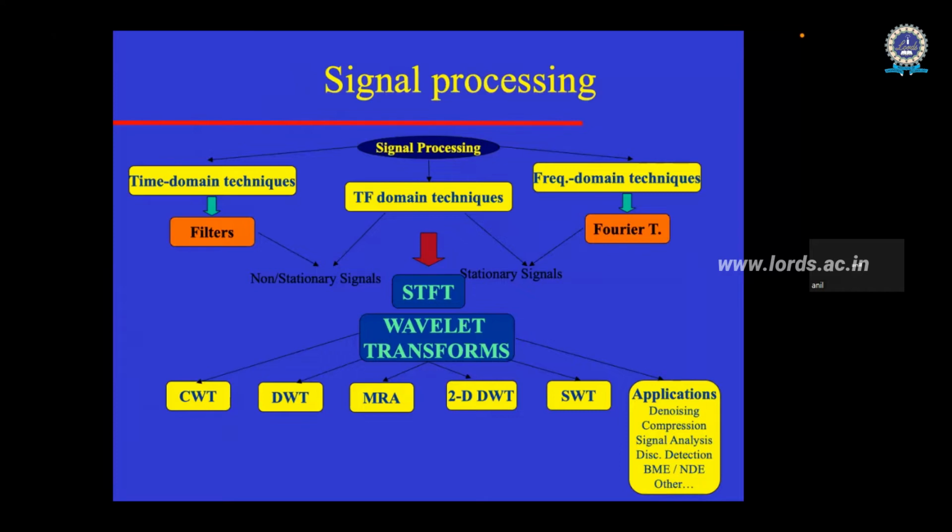In joint time-frequency analysis, there is no perfect joint time-frequency representation because there is an uncertainty. You know, f equal to 1 by t, right? I want to see both f and t properly. But f equal to 1 by t means frequency is inversely proportional to time. So there is uncertainty. You can't see all of them well, and also there is not a unique representation. So that's why there are a lot of techniques for joint time-frequency representation.